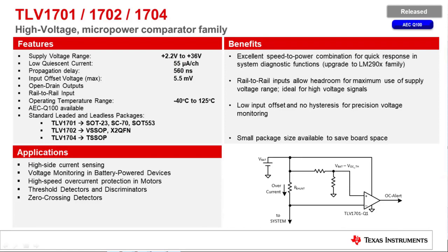So you can look at it 2 ways. If you're using LM2903 today or LM393, TI standard comparators, we have the B family coming out, which the 2 dual channels are already sampling today and available. That will be your small step upgrade to your existing parts. That'll be the best supply, and it'll have slightly improved specs. If you say those standard comparators just really aren't doing enough for me in my system, I need lower power or I need faster response time, then you can consider this family. It still works at the same voltage levels, so you have no sacrifices there.